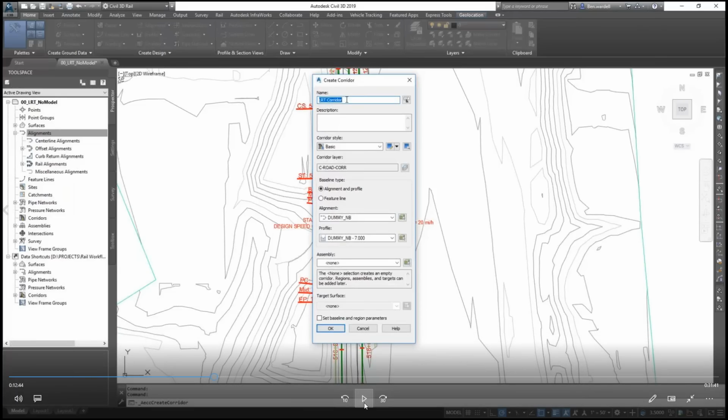Can we create our own subassemblies? Yes, you can. And I didn't get into that, and I do apologize just because of time constraints. In the subassembly composer, that's something that I did. If you noticed on the bridge subassembly, I actually put together a direct fixation subassembly for that. It's fairly intuitive. You draw it from point to point. You can draw the shape of the rail, you can draw the shape of the plinth itself. And it's fairly simple to do.